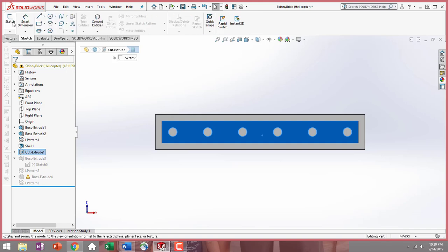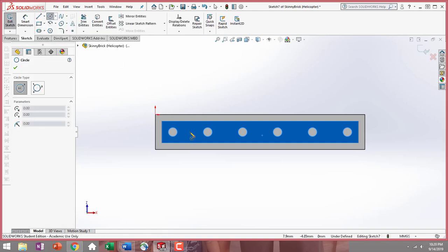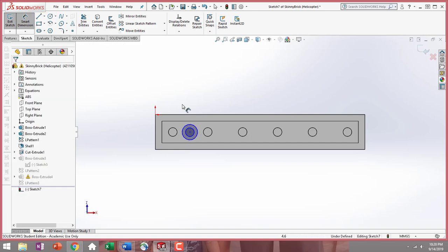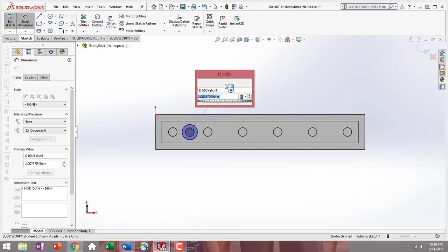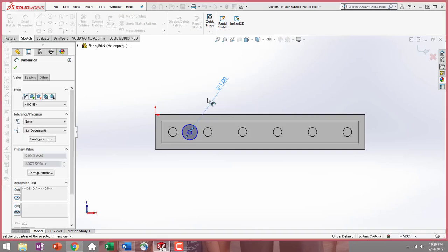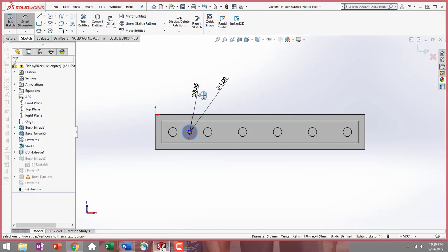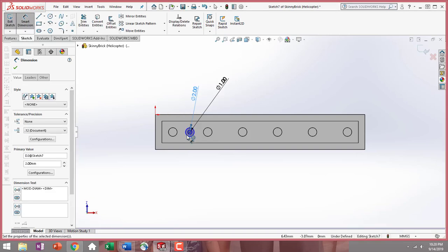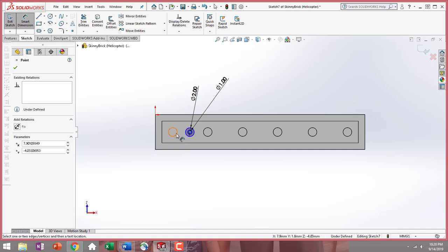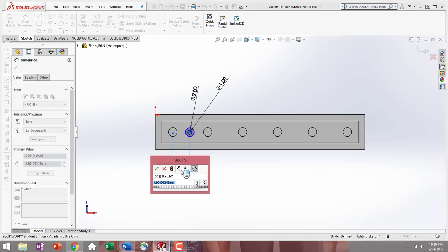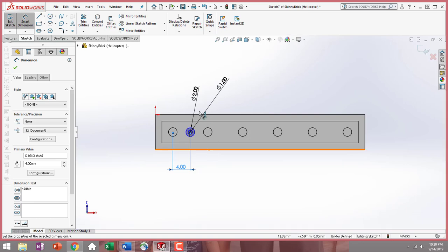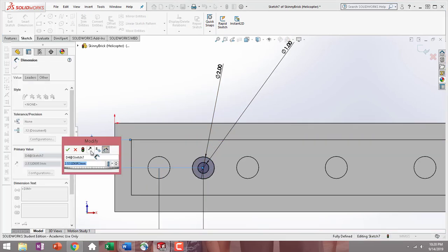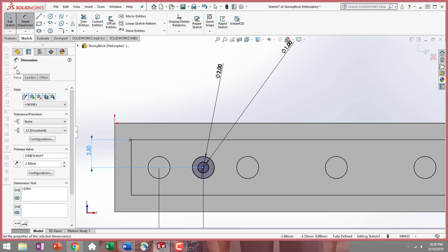Go to the Sketch tab, open up a new sketch, and create 2 more circles within themselves if you are creating a new one. You do not have to. I'm going to move a little faster on this since we just did it. Remember to dimension that inner circle 1, our outer circle 2, a dimension of 4 in between, then a dimension of 2.5 to center it.